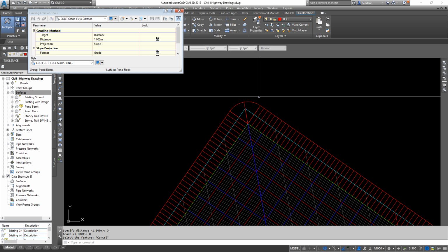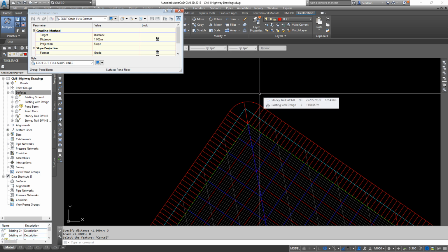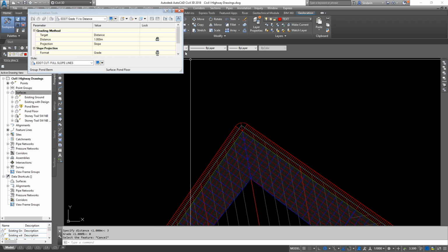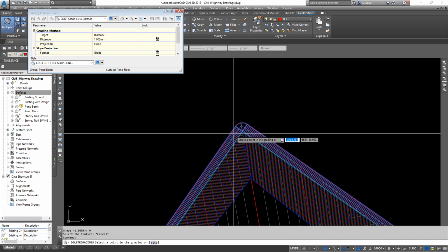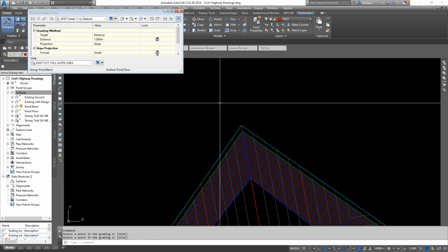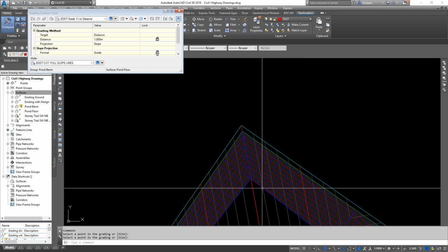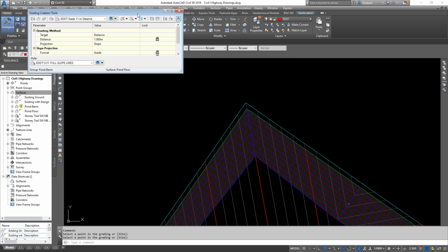Now, they don't build things round in real life. We need to create a square here. We need to square this off. It can't be round. So I'm going to use the delete grading command. So delete grading. I want to delete that one. Hit enter. Now again, do not undo. Don't use the regular delete command. There's specific grading delete ones that keep your drawing clean.